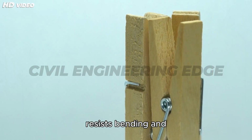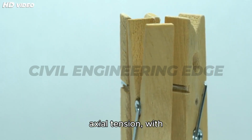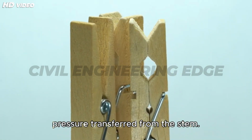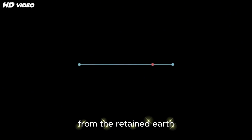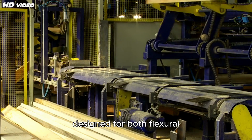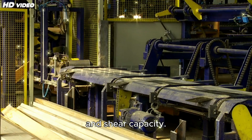The counterfort resists bending and axial tension, with critical load coming from the lateral earth pressure transferred from the stem. The bending moment and shear force are computed considering the pressure from the retained earth acting perpendicular to the stem. The cross-sectional area of the counterfort is designed for both flexural and shear capacity.